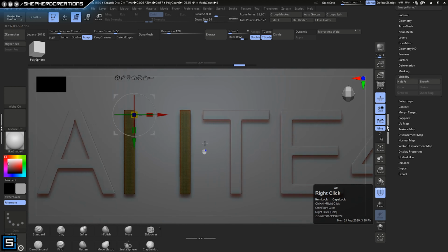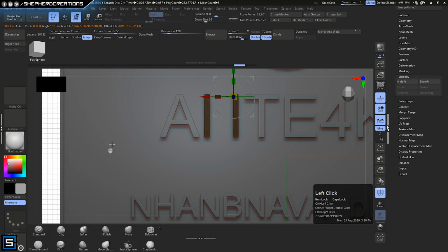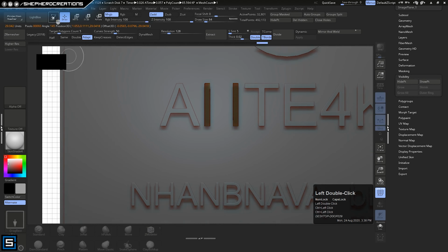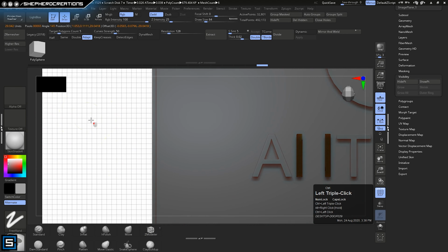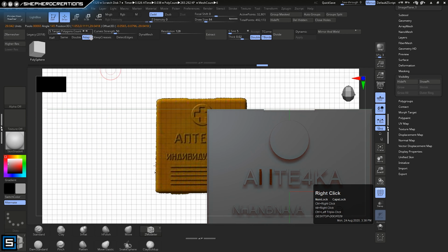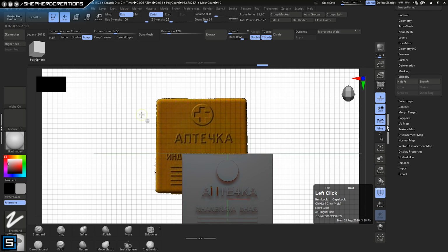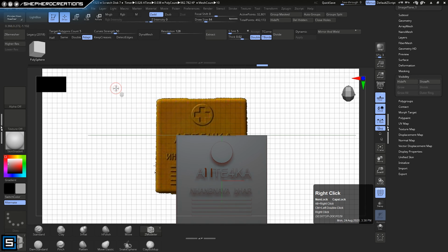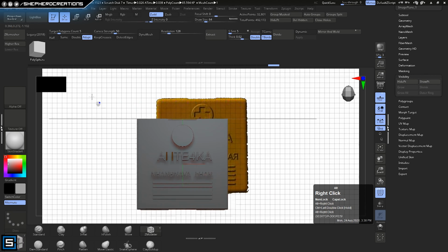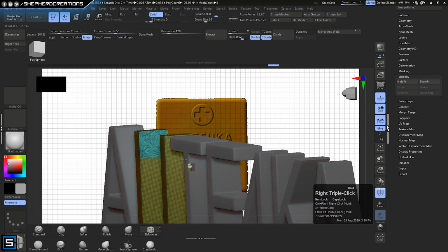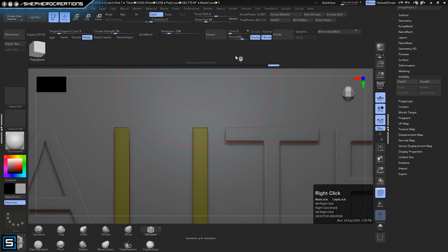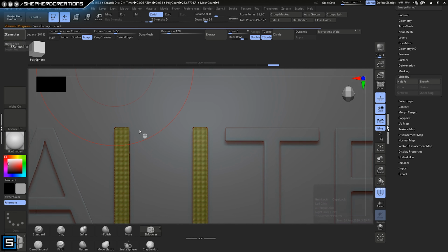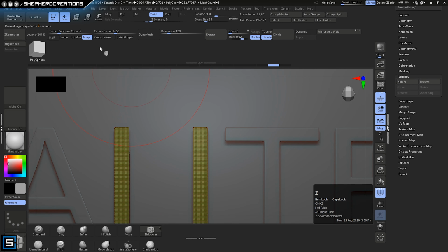And it's not working exactly the way that I want, because whenever I deleted that area by hide point, delete hidden, and closing the hole on that object, it needs to be remeshed. Okay, it needs to either be ZRemeshed, or I need to do Dynamesh, because you can see that the polygons in that area are not very consistent. They're all random shapes. So I'm going to ZRemesh this with a decently high resolution.